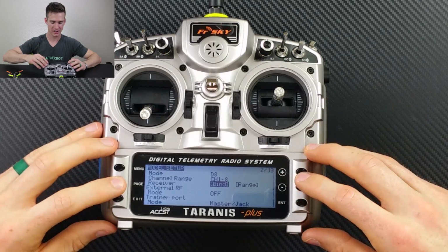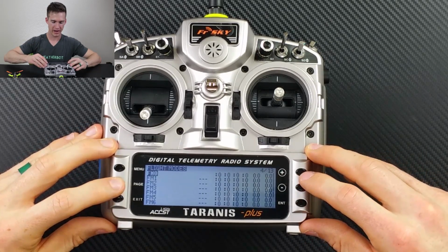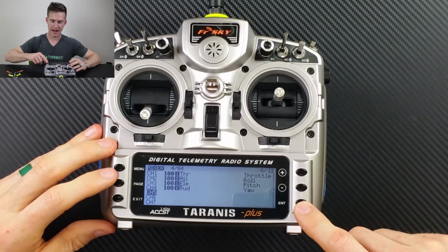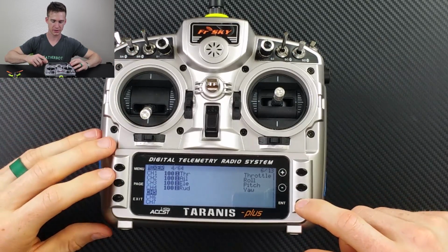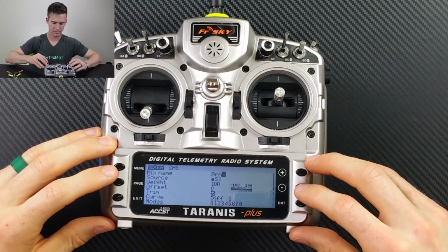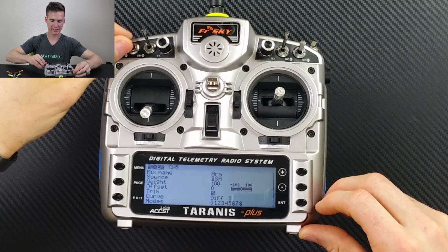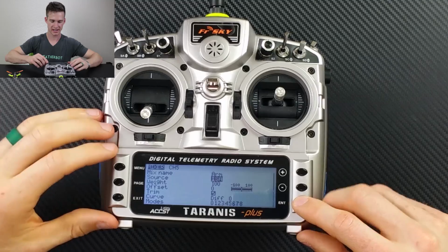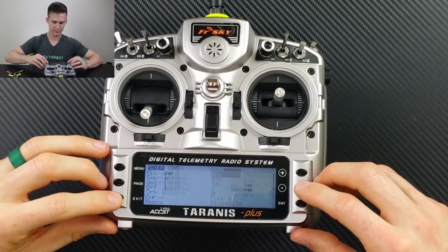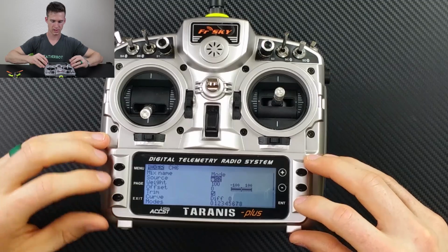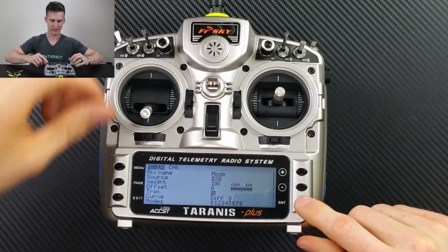So we'll go page over. We'll keep paging until we see the mixer. So channel 5 is going to be our first auxiliary channel for arming. And then we select enter when it's blinking, then we can hit this switch and that designates this switch to SA. Very good. And we'll go channel 6, which will be our second auxiliary channel, and we'll designate that with SB.